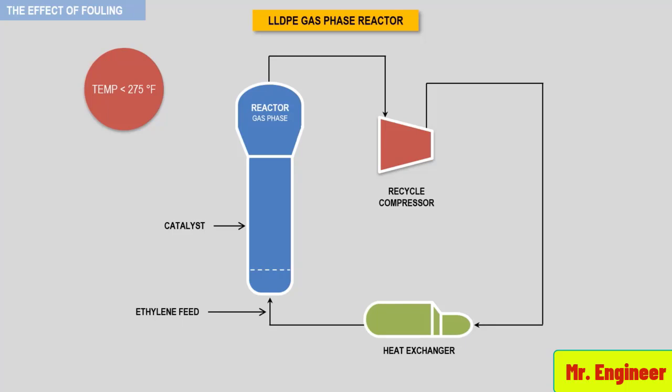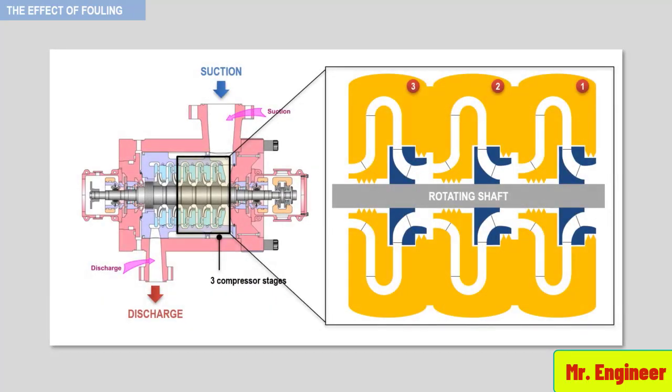Now, as we have learned in previous sections, process gas temperature change within any compressor is a function of compressor efficiency. Therefore, compressor stage efficiency deterioration due to excessive stage seal clearances, impeller erosion or axial misalignment can initiate fouling in these processes. Most centrifugal and all axial compressors have more than one stage, as is the case for this centrifugal multi-stage vertically split compressor.